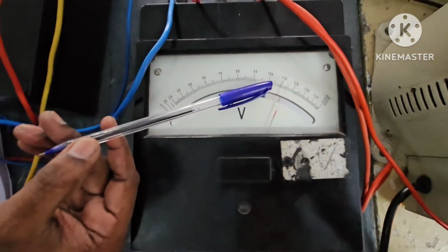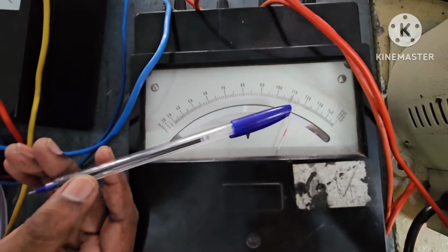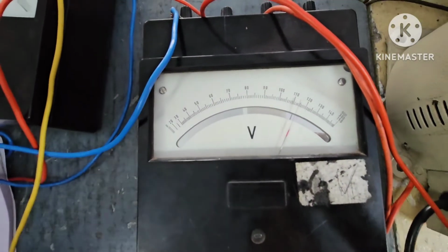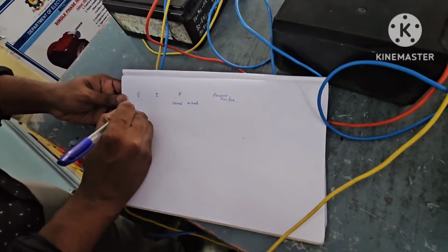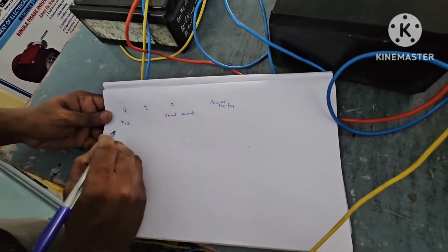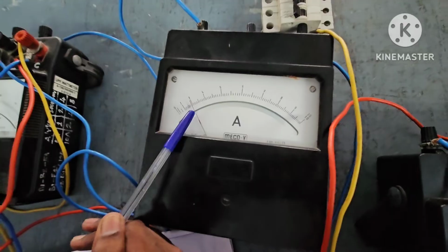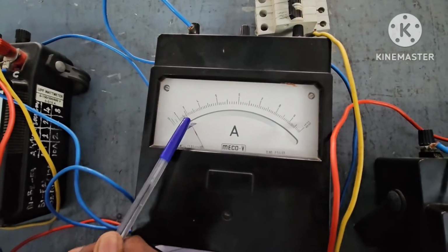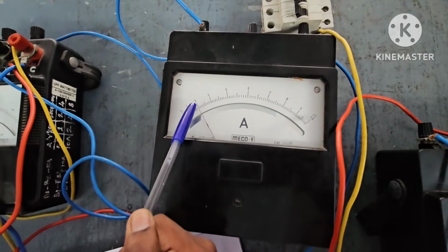First, measure the voltage. So you can see voltage almost same, right? 230 volt. So I record the voltage now. Actually we are seeing over here 115, which needs to be multiplied by 2 because we took from the 300 volt range. Then I'll measure current. You see current is about 3 ampere. We are connected to 10 ampere range, so I can take it as it is. So current is 3 ampere.